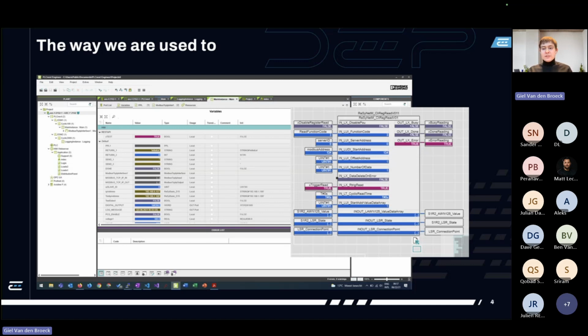You need to pay attention to which function codes the block has, where's the server address. Modbus TCP, Modbus RTU, all come with their particularities. And although each device lists that it's Modbus TCP/IP, they all have their different flavor of how they implement and use it. Some devices, for instance, allow you to read at millisecond levels. The other ones are like, yeah, you need to respect a 200 millisecond read interval, otherwise our Modbus server will basically crash. So that's actually the mindset you're in at that point.